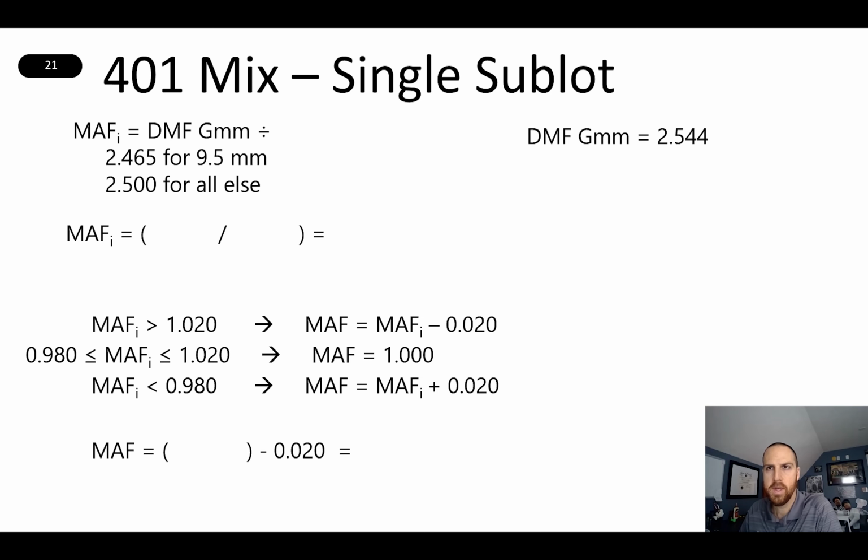NDOT accepts HMA, or pays for HMA, by the ton. So if you have a heavier mix, even though we're paying by the ton, and you would say we paid for 1,000 tons of mix, it actually would not go as far as a mix that weighed less. So it's all about trying to get the payment for the asphalt back into a normalized tonnage, so that we're not short or over on material. So this is how it's calculated.